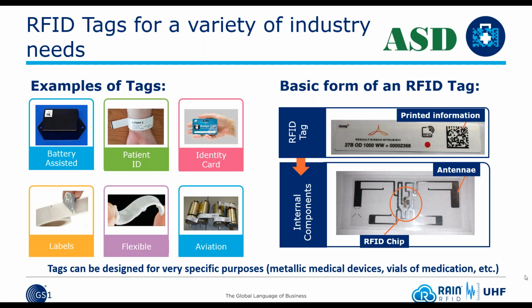So it's kind of stealing some of the active tag's thunder, if you want, in that it does have a battery, and what that allows for is that the read range can be further. It's not that it continuously pings. The concept is still that the reader emits the signal, but the BAP tag can be further from the reader, allowing it to respond.